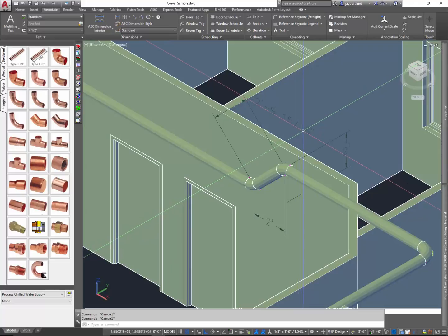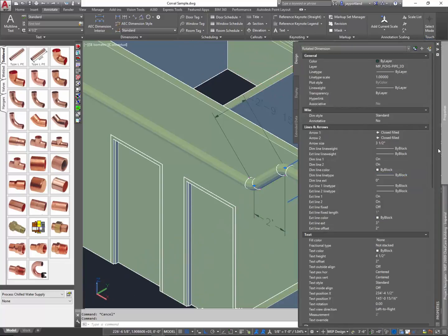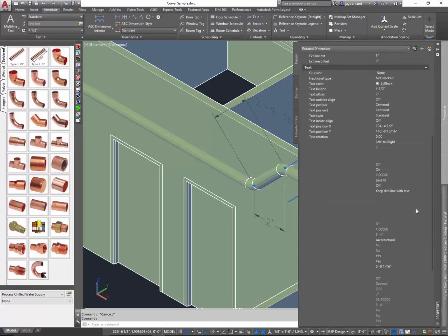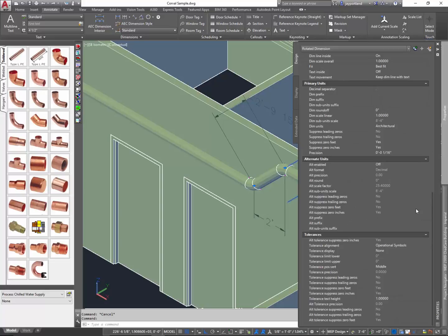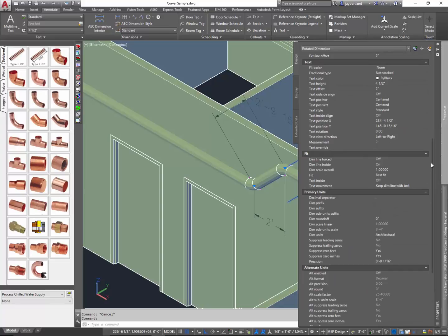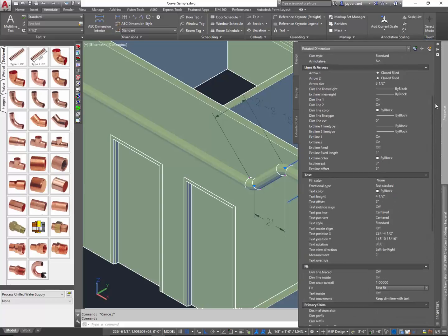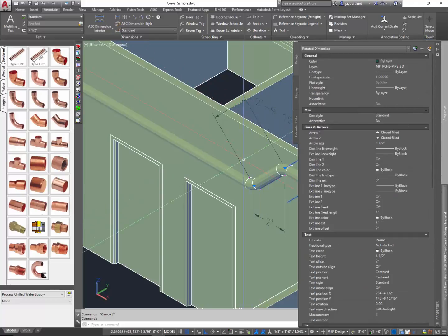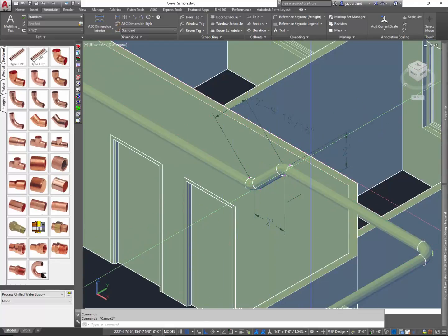I think there's even a way that we can oblique the text itself. So once I select that spool dimension, I can come in here and oblique that text if I remember right how to do that. Where is that control? I'll have to look that up, but I thought there was a way that we could oblique things. So best fit. I forget how to do that. It's not important. What's important is getting the dimension in space there. So absolutely ways that we can document that both in 2D and 3D fully dimensioned.